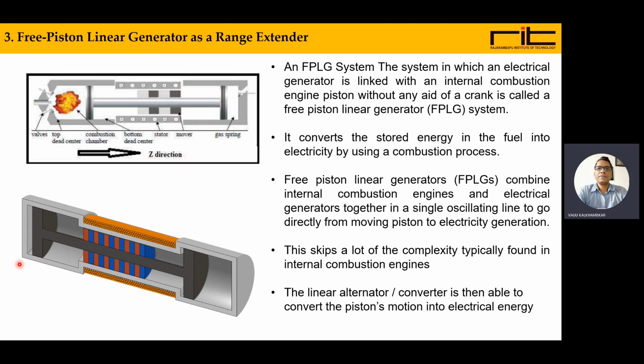It's called a free piston linear generator, that is FPLG system. It converts the energy stored in the fuel into electricity by using a combustion process. Free piston linear generators combine internal combustion engines and electrical generators together in a single oscillating unit to go directly from moving piston to electricity generation.